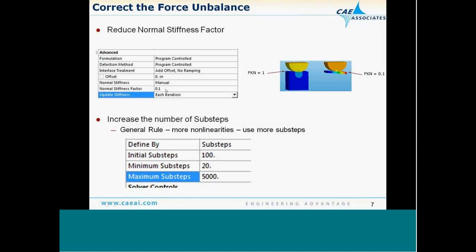And the normal stiffness factor that is useful is problem dependent, but generally speaking, somewhere between the high end, maybe 10, and at the low end, I may use like 0.01 for very flexible bodies. So you're looking at somewhere in that range.